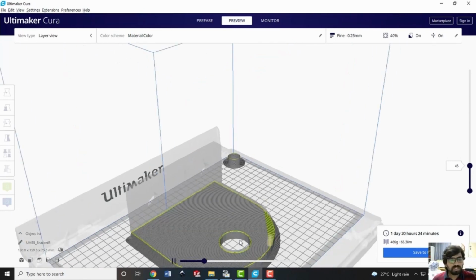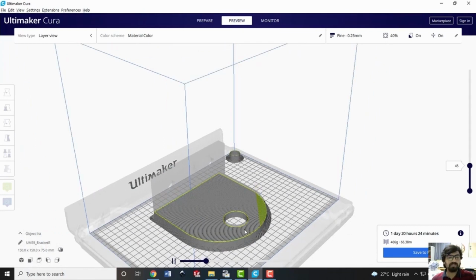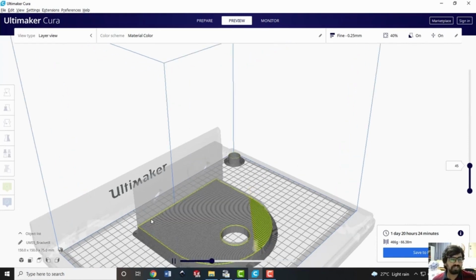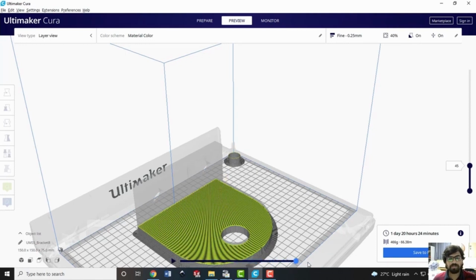But unfortunately, right now in this layer there is no support mechanism, so you cannot see that. But we will consider a layer where there is a support as well. So you can see first it deposited 3 passes for the outer boundary by the contour parallel strategy that if you remember we have already considered in the shell criteria of the process parameters, and then it is filling the inside area by utilizing the zigzag strategy. So you can see the tool is moving back and forth utilizing the zigzag strategy. So let me move faster here now, and this is how the layer is completed.